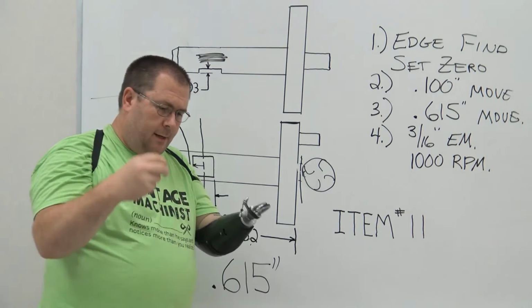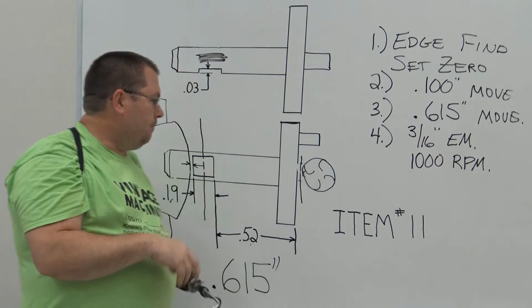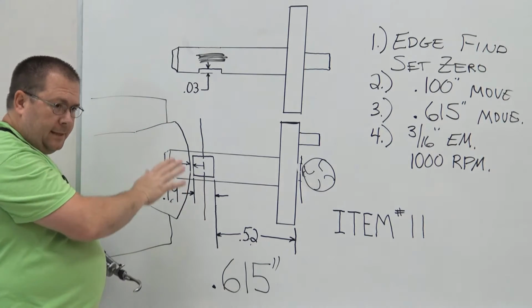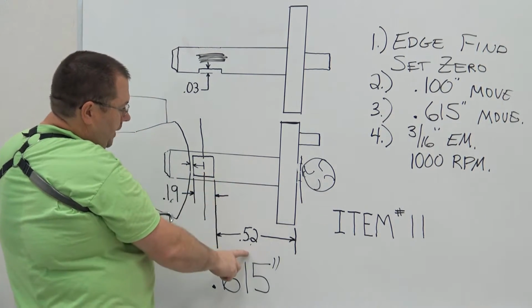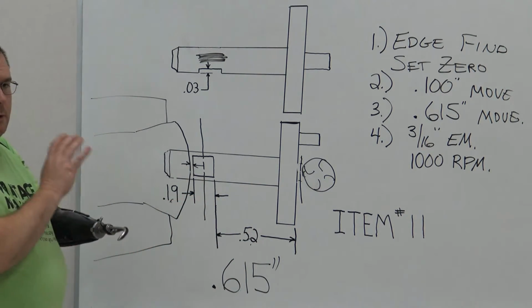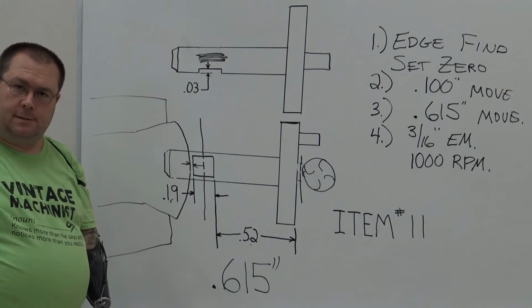Okay? You can double check with inspection, make sure it fits inside of your flywheel. But aside from that inspection, as long as it goes in and you've got that nice flat on there, you can take your calipers and measure 520, make sure it fits inside your flywheel, part's complete. Now we're going to move on to our piston.